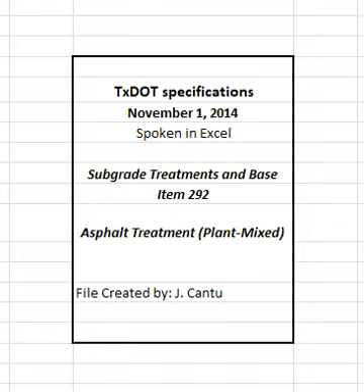4.6.3.3 Production binder properties. The engineer may take cores or other production samples at random from the project to determine recovered asphalt properties. Asphalt binders with an aging ratio greater than 3.5 do not meet requirements for recovered asphalt properties and may be deemed defective when tested and evaluated by the construction division.